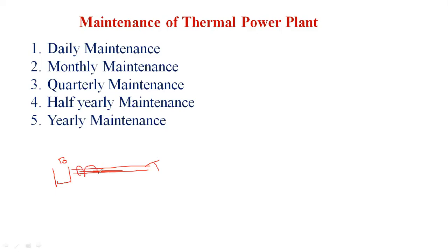On the pipeline, they apply gunny bag with lime to prevent steam leakage, because in a thermal power plant the efficiency we get is about 29%. By reheating in the intermediate stages we improve the efficiency by only 5 to 10%. The overall efficiency we get is only 30 to 35%.